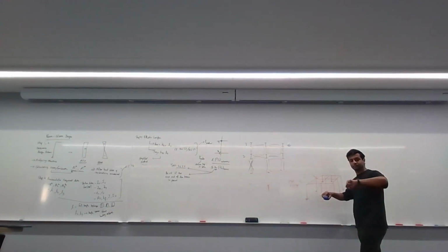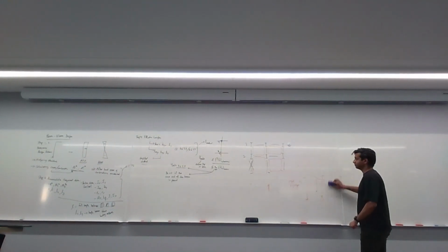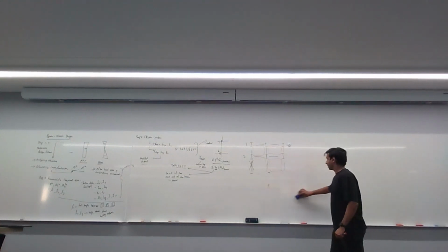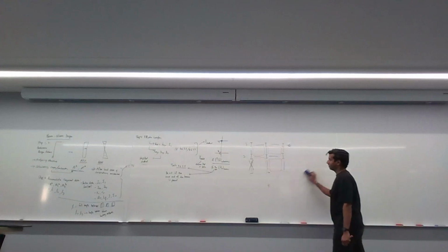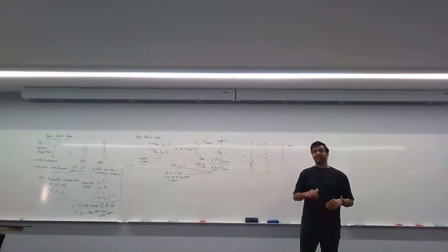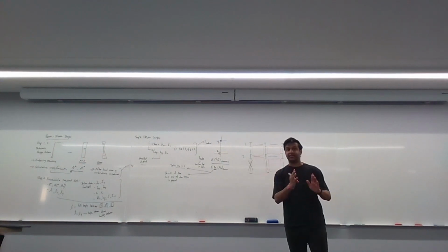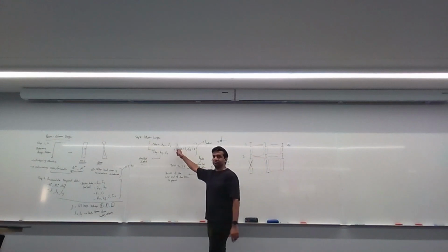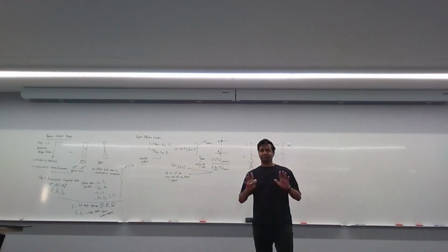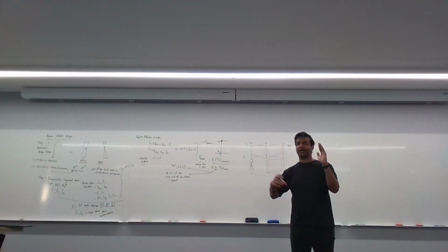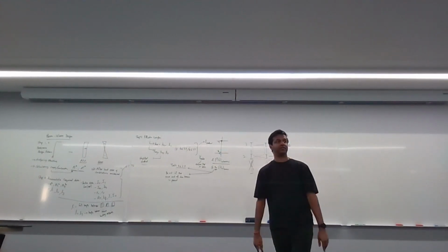For the columns, when we're doing the gamma method, are we using Ix or Iy? It depends on which direction you're looking at. If you're using the gamma method to identify the effective length in the x direction, then you're using Ix. But then you've got to do the same thing for y, because you need both. So remember, for the design of the column using beam column, you need to analyze it in both the x direction and the y direction.